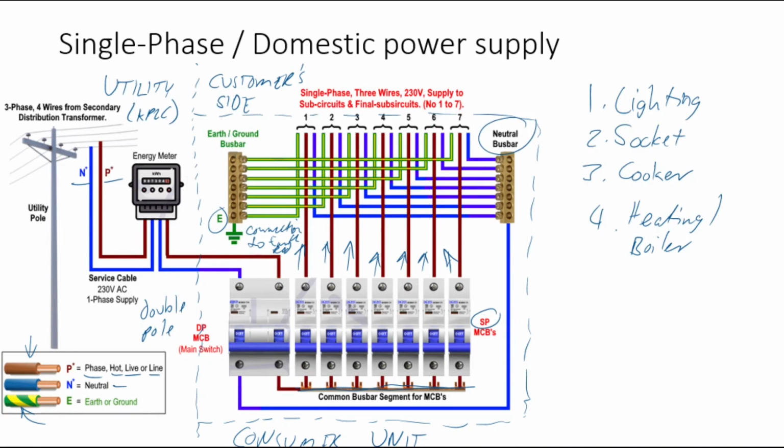Usually when you have a lighting circuit, you will generally have 7 to 8 lighting points, depending on the type of circuit, but there's a large variation of what you can have, either LED, fluorescent, and so on and so forth. We will go through this in a topic on lighting. These are usually thin cables, so 1.5 mm squared or 2.5 mm squared.